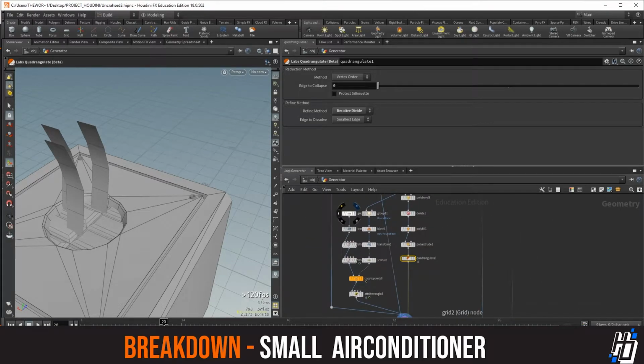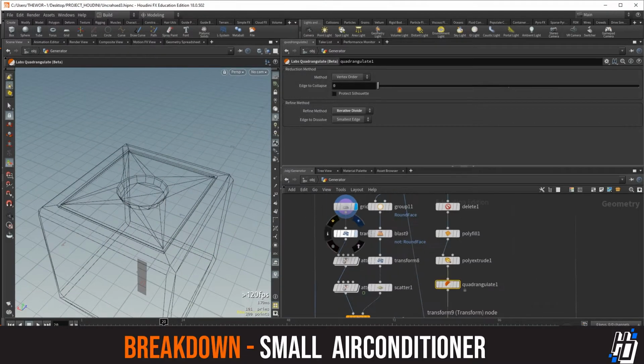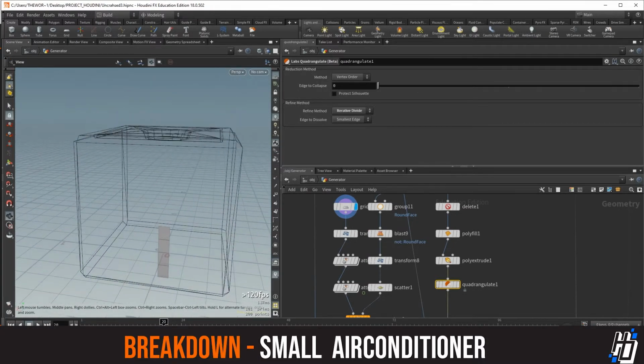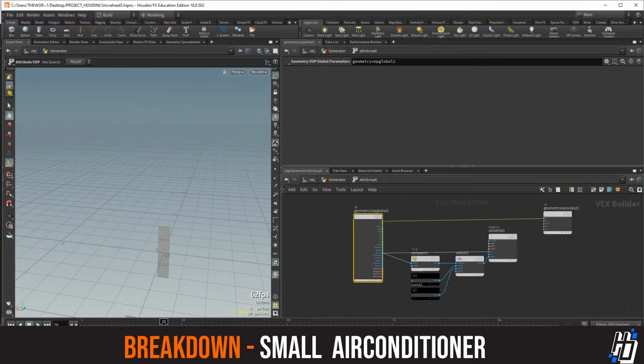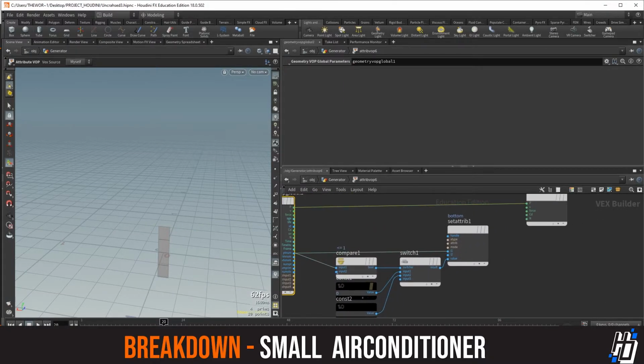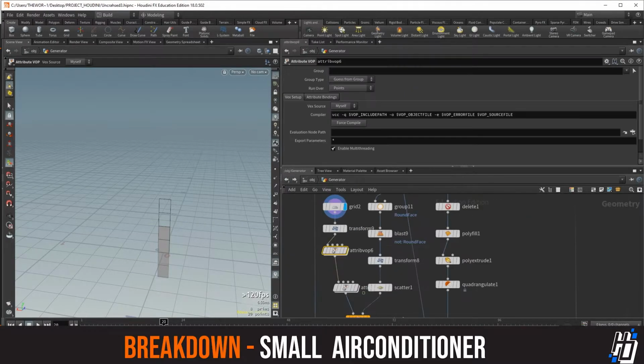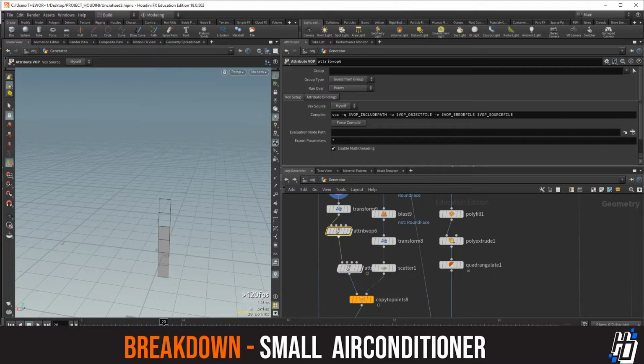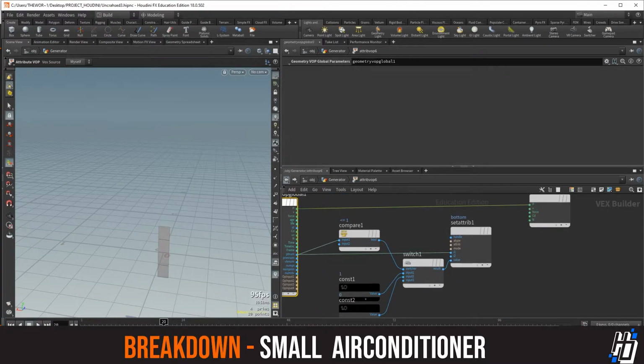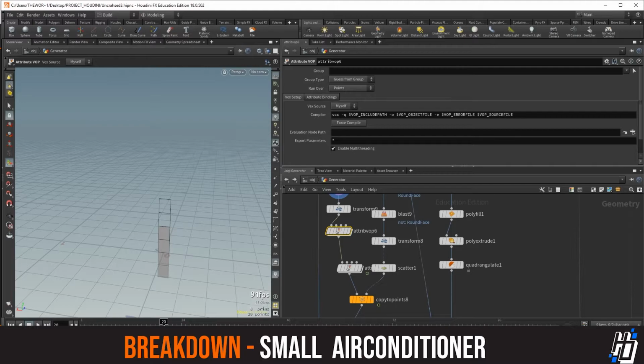Output, and now for the animation, I just made a plane, a grid. Then I scaled it to the size that I wanted, and used the transform node. Then attribute VOP with a simple switch node to only select the bottom, don't move the bottom, give it an attribute that we use to multiply. So 0 means don't move it, 1 means of course just move it.